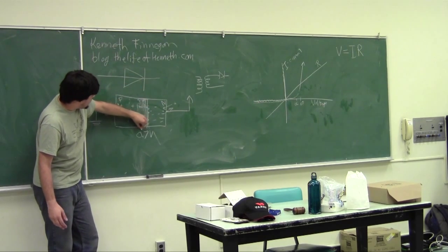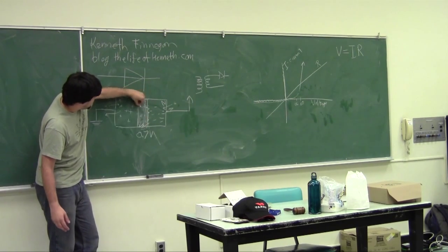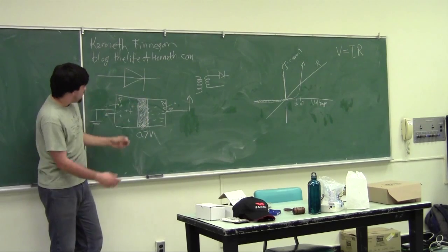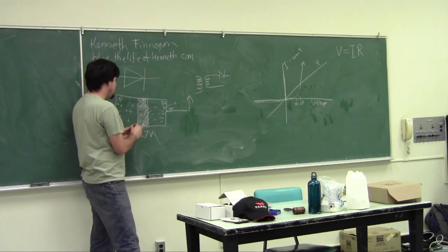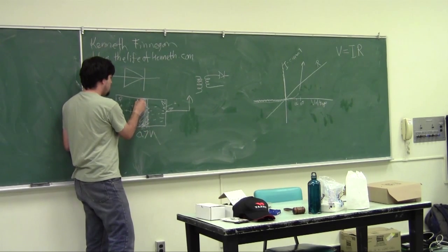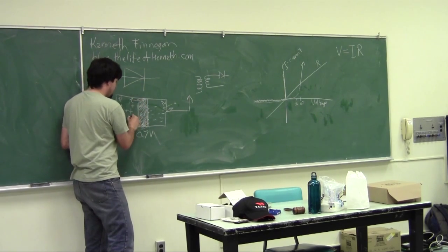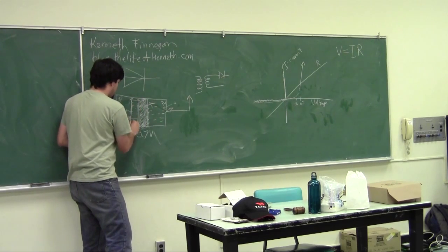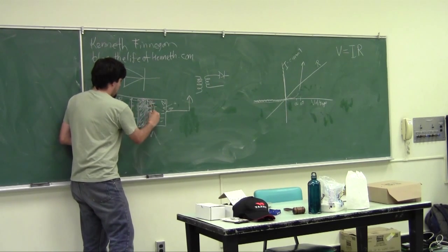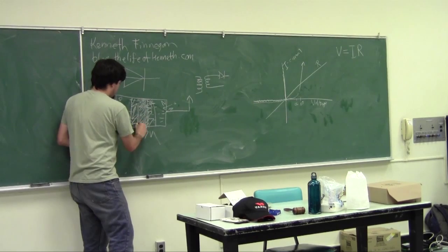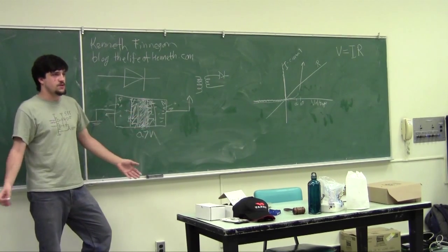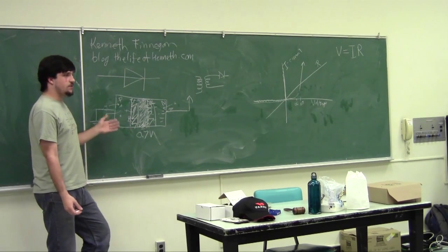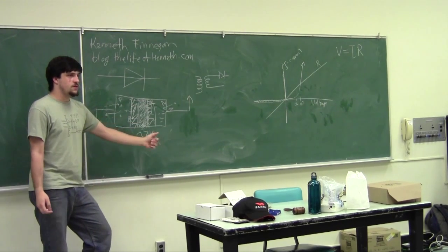When we have the diode just sitting there, we have the 0.7 volt depletion region in the center here. As we apply this electric force to it in the opposite direction, this depletion region instead grows, right? But the fact that it grows isn't particularly important. As long as it still exists, there is no current. So that is why diodes only pass current in one direction and not the other.